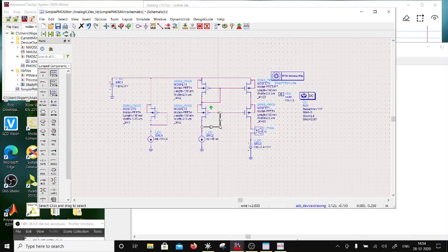It means that if I connect this from here to, let's say, here, and this one from here to here, so I'm forcing here twice of V overdrive plus Vt, and V overdrive plus Vt goes out here, so I'm left with V overdrive here. So I'm forcing a voltage of V overdrive at the drain to source of this device rather than V overdrive plus Vt. But I had a price to pay.